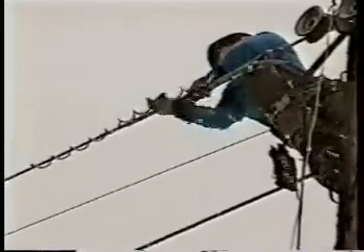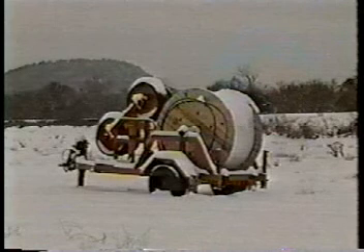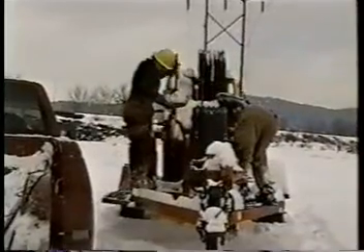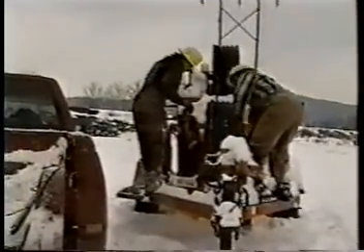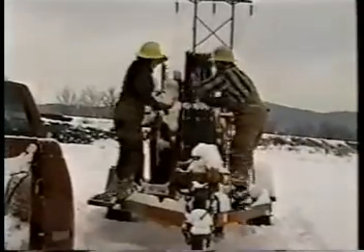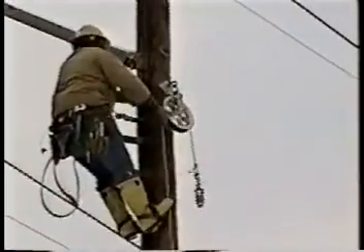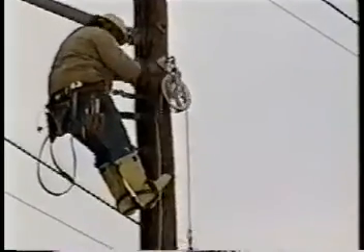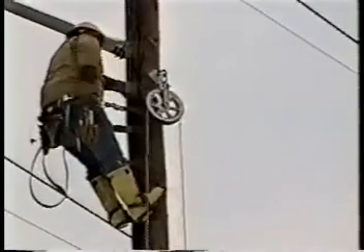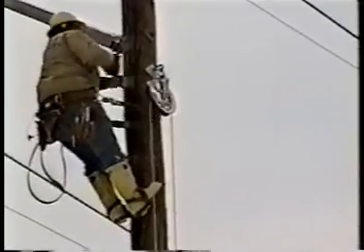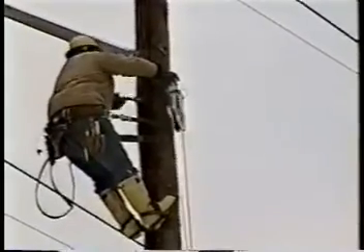An efficient way of installing self-supporting cables is the backpull method. The cable reel is placed on a reel stand or trailer at a stationary location. Here, a tensioner is placed in line with the cable reel and aerial structures. Cable clamping hardware is installed to the structure at the appropriate height, and travelers placed just above or below the desired framing location of each support structure.